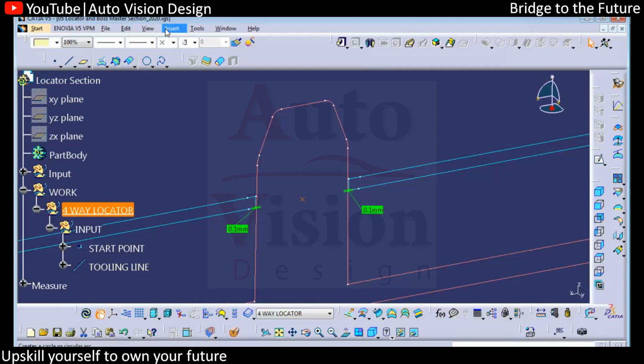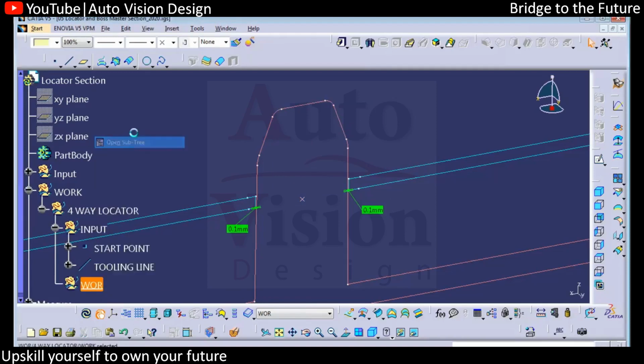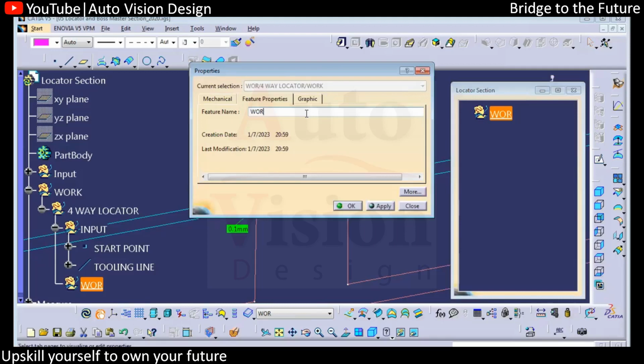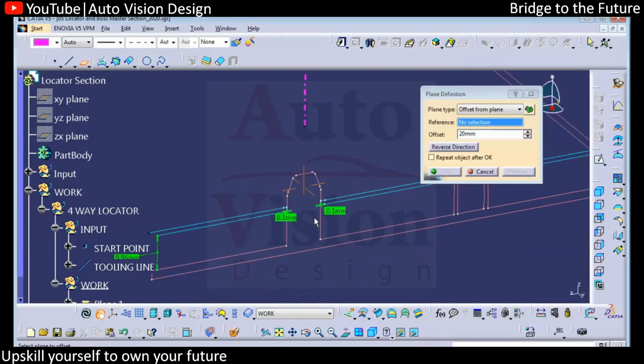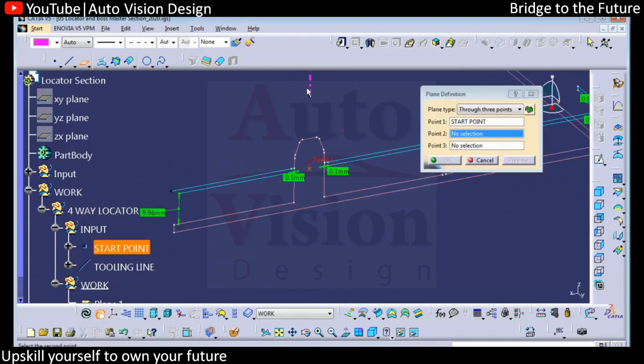Then again we have work. So in that we can add work, whatever geometry we're going to create for this four-way locator. Then we need to add a plane normal to the line passing through the point. Normal to the line passing through the point.